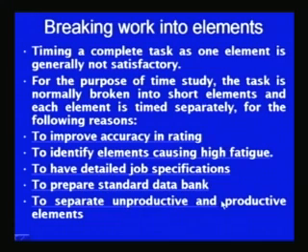So, development of time values for small elements which are repeated in various operations helps to develop the standard data bank, which can be used for time study in the standard data method and also in the predetermined motion time study method. And another objective of breaking the job into elements is to separate the productive and unproductive elements. Identification of the unproductive elements helps to improve the method, so as to reduce the ineffective time and set the standard time in such a way that it can be done in the least possible time, and a more accurate time standard is set for the performance.